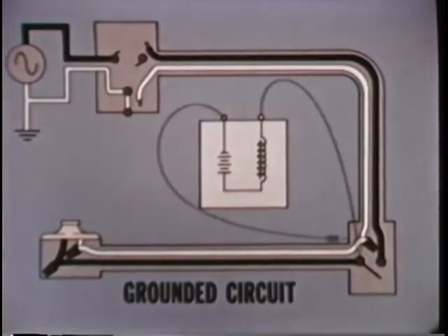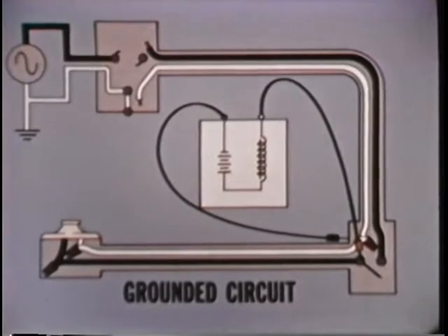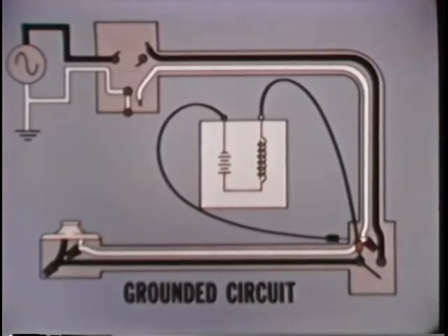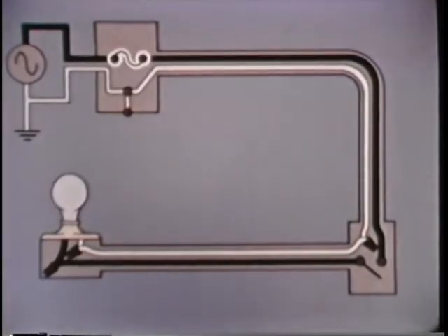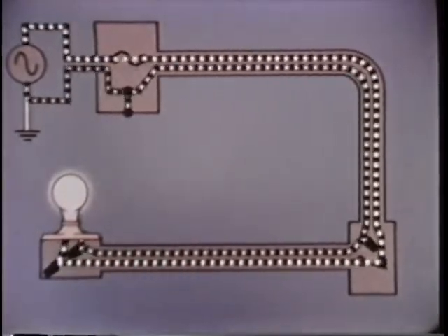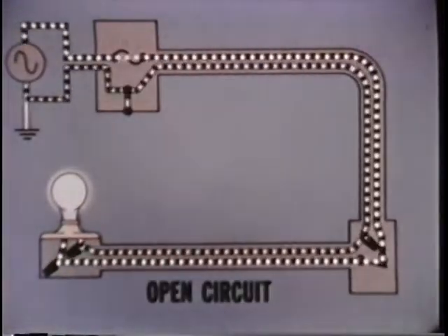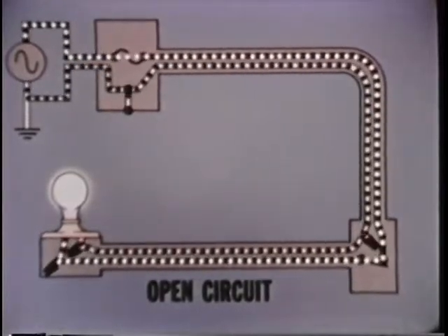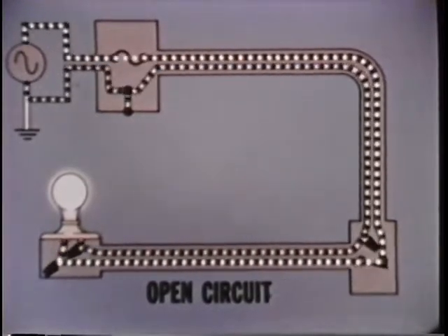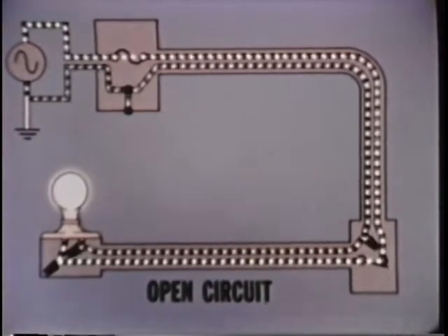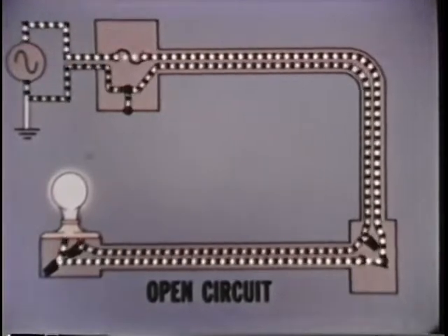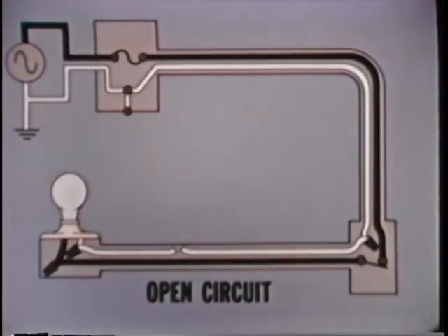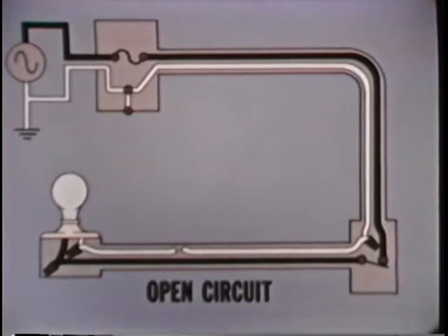The ground is removed, and the circuit is retested at the trouble point, and all connections are restored. The light and fuse are replaced, and when the switch is turned on, the circuit is back in service. Perhaps the most common trouble in wiring circuits is an open circuit. In lighting circuits, the most common fault is a burned-out bulb. But sometimes the trouble may be caused by a loose or broken wire, requiring troubleshooting to locate it.